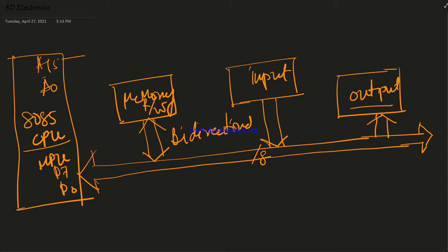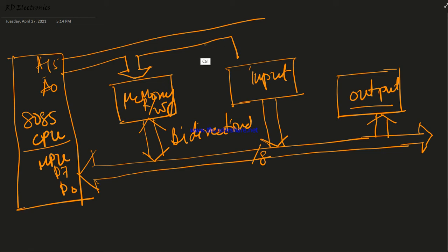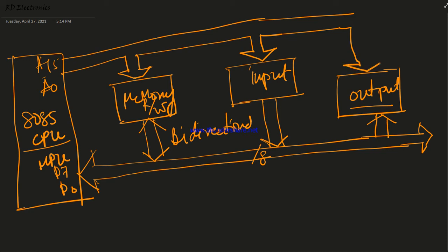And this one is quite important, A15 to A0. This is called the address bus, and here we connect the address bus to the different types of peripherals. The first one is connected to the memory, the second one is connected to the input output device for mapping the input output ranges. In the next video we will discuss the IO map interfacing techniques.